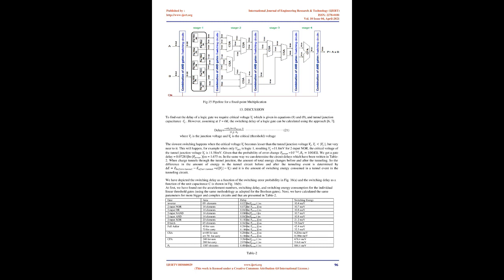The CSA operations are performed bitwise simultaneously on a column of digits to generate two n-bit numbers, a sum vector S and a carry vector C. Note that the leading bit for the sum vector S is a 0 and the tail bit for the carry vector C is a 0. The input-output relationship will be expressed by the equations given in 19 and 20 for i equals 0, 1, 2, and so on, where the first operator indicates exclusive OR, AND, and the other indicates logical OR operation.